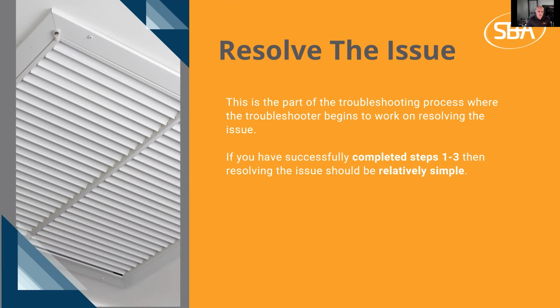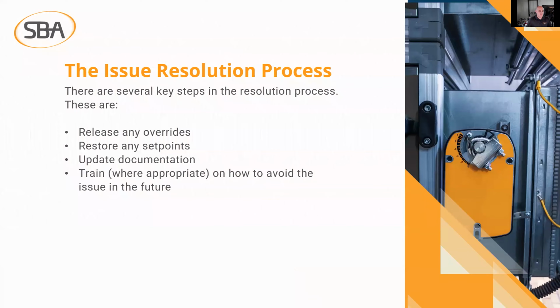I recall a music studio that was all wood, that was designed with a fan coil unit that was cooling only and had no form of reheat. And the idea was to take outside air, and this was in the South, in the middle of summer, and mix it with the cool air, and somehow that would lower the humidity level, not paying attention to the fact that southern air is 70% relative humidity at 90 degrees. There's no way, if you follow a psychrometric chart, that could fix the issue, right? That's a complete re-engineer solution. So it usually is relatively simple. It's not always easy. All right, let's continue.